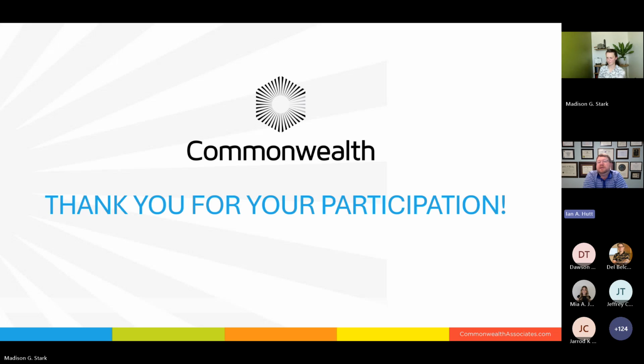For breakers, can the interrupting current rating be used if it's larger than the asymmetrical current? For example, if the asymmetrical current is a value and the interrupting current rating is a higher value, is that acceptable? I think is maybe another way to state that. Yes, you would like your interrupting current rating to be greater than the asymmetrical current available at the site. Does that answer the question? Yeah, I think so. Yep.